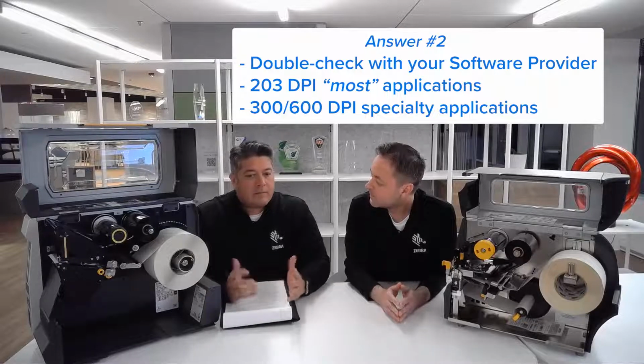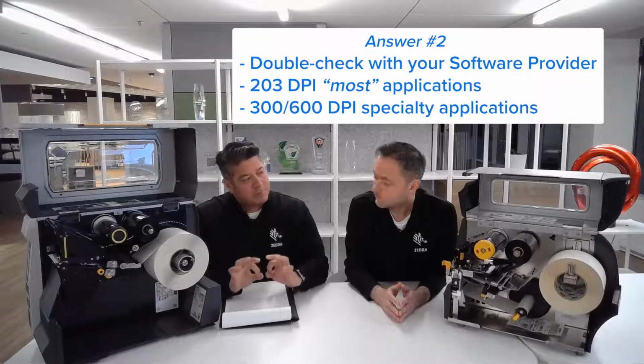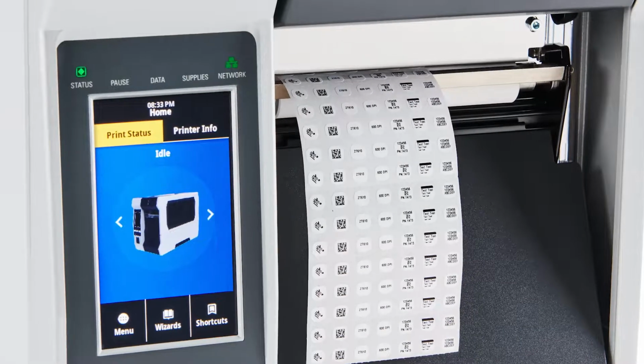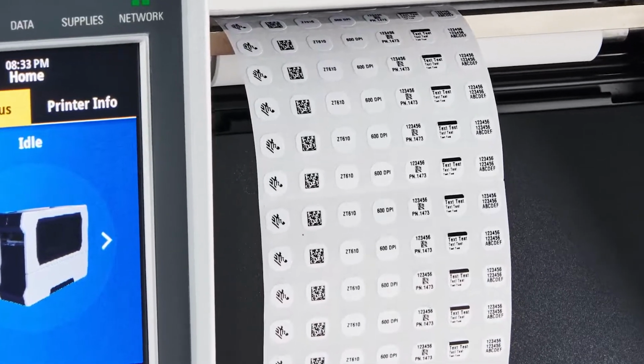Yeah, because I have a lot of electronic component manufacturers, and if you think about it, if you break open a laptop, you see these small labels with 2D barcodes on there. What are your thoughts on that? Yeah, those are what we call micro labels. So those really small, teeny tiny barcodes really need to be printed at a 600 DPI print resolution. It really gets that fine detail needed so the barcodes can be scanned.